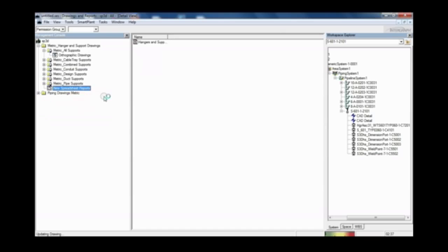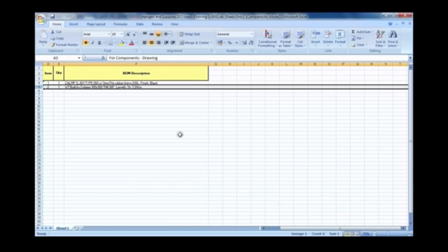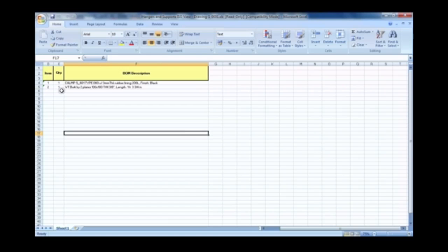Using different types of dimensions according to your support standards. So I'm going to extract the MTO of this particular support, or this entire model. This MTO format we can customize according to the requirements, client to client, on how they want the MTO to appear. For example, they may want the quantity in the end, the tagging to be different, the description to be different. Those kinds of customization we can do. This is a sample MTO which we are showing for demonstration purposes to prove that our support is well customized and rule based, and you will automatically get the MTO and fabrication drawings as per your requirement, and the support will always be constrained, with all the rules or laws applicable to placing that support.